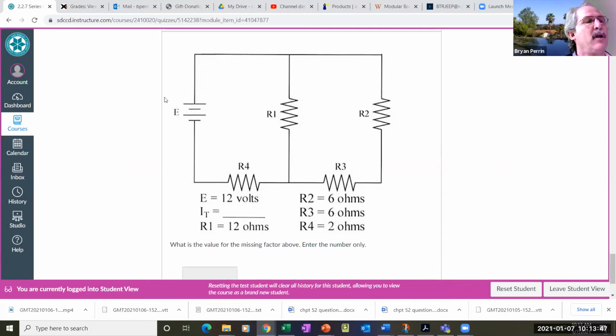So if I go from here to here, there's a parallel circuit. I go from here to here is another parallel circuit. So this loop is parallel to this straight line. So that's why I'm able to add my R2 to my R3, because this is one circuit. There's no power or ground between these two resistors. So I can treat them as one because they're in parallel to this circuit, even though it only has one resistor. Does that make sense?